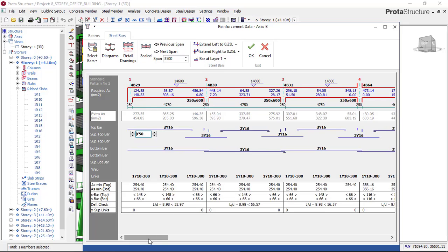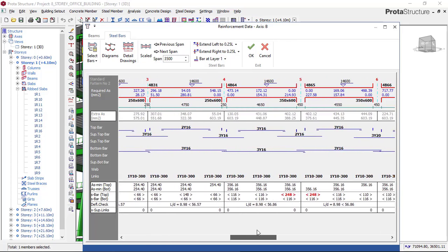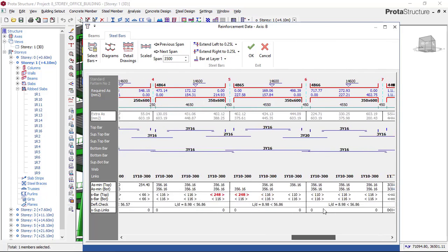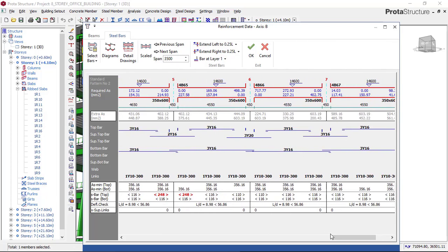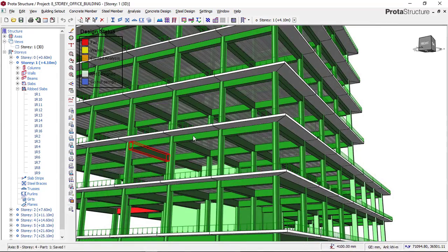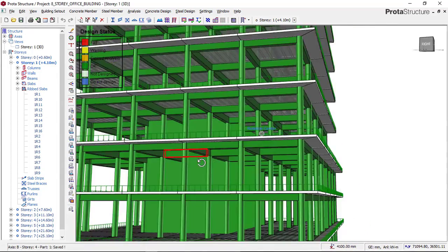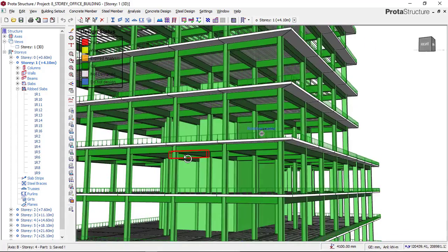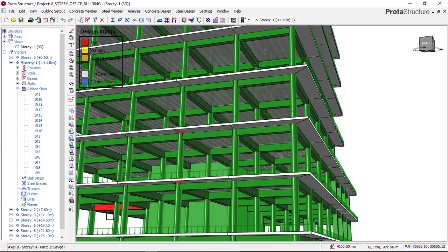Okay, so right now we check on this, and then go over and check on this. These are perfectly okay because everywhere is okay, and the set of reinforcement given to us is perfectly okay. And this is okay. We then go ahead and check on the next floor, which is the 3rd floor, if all the 4th floor members are okay. So let us check if the 4th floor members are all okay. You can see that they are all okay right now. So let us go and check on the 3rd floor, because on the 3rd floor we have one beam failing here.